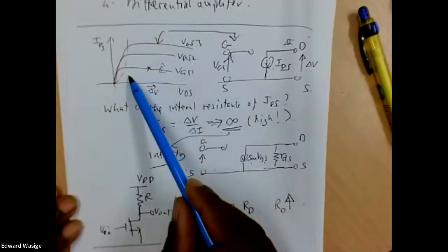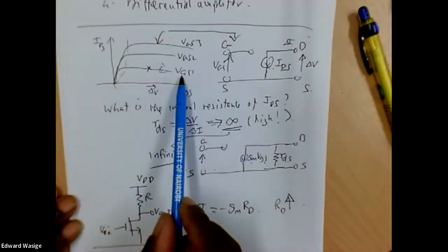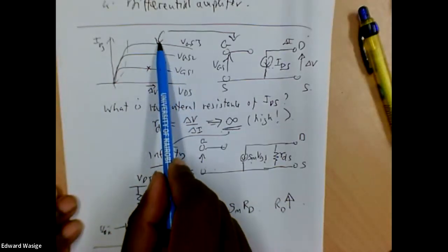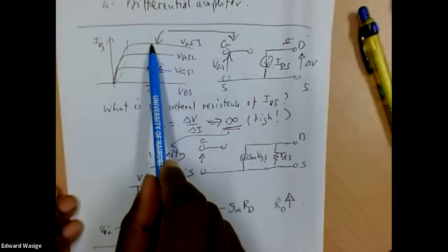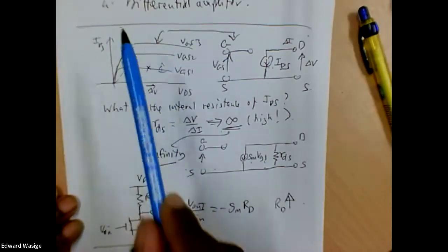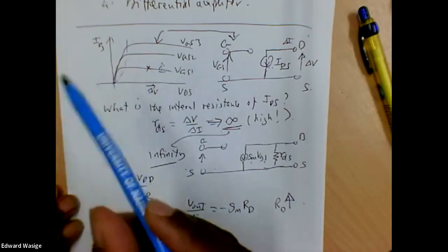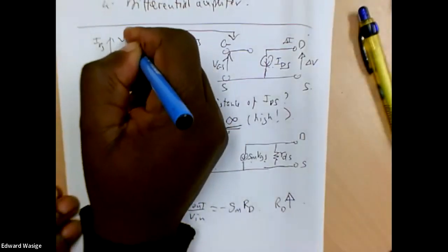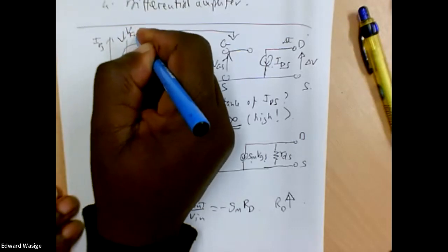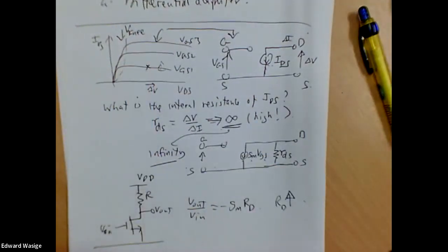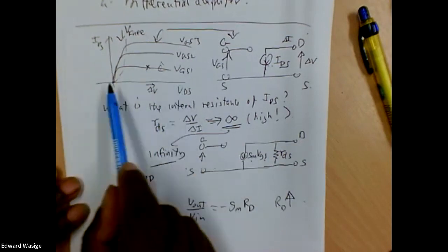So just one thing. This is VG. As the gate to source voltage increases, the current through the device also increases. The point at which this voltage, we call it the knee voltage, as I've already mentioned, is the point at which the current saturates or flattens out.